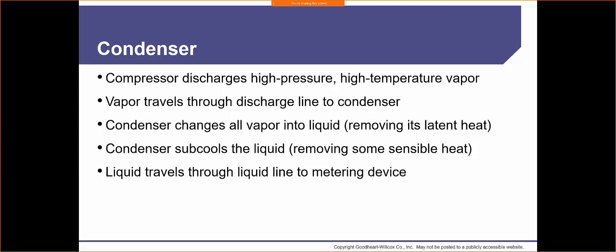We've got that heat that is being absorbed by that pop can. We've got heat that's being absorbed into the refrigerant via the process, and we've got this moisture. Our dew point is reached because we're dropping our temperature, and so that moisture starts to condense. Now we're removing latent heat. We're turning that vapor into liquid, so we're removing the latent heat as well as the sensible heat.